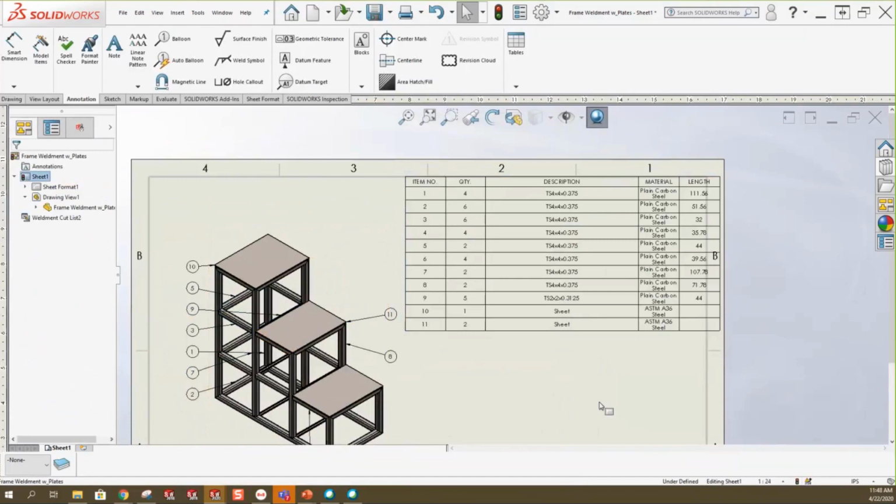Now, a step above this is, what if I do have something unique? I've got these kind of funky looking cuts, these mitered corners, right? How do I show what one of those looks like? I can do this with any drawing. So this is going to eliminate the need for me to make its own part file. And by the way, everybody's like, well, can you save those out as part files for the bodies? You can. Whole another half an hour discussion I'm not going down.